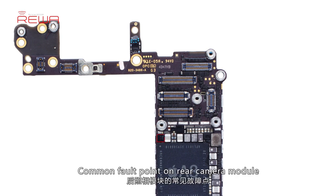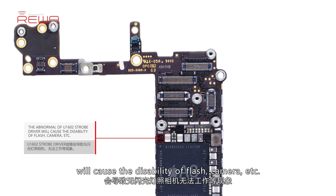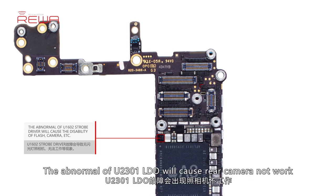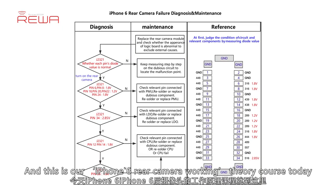Common fault points on the rear camera module. An abnormal U1602 strobe driver will cause the flash, camera, etc. to be disabled. An abnormal U2301 LDO will cause the rear camera not to work. And this is our iPhone 6 rear camera working theory course today.